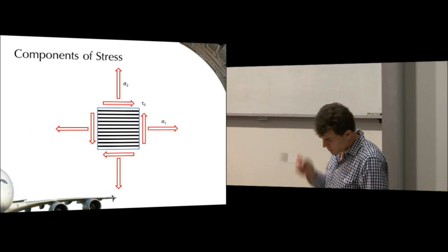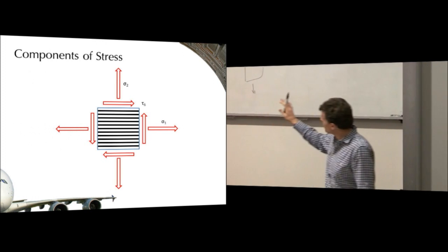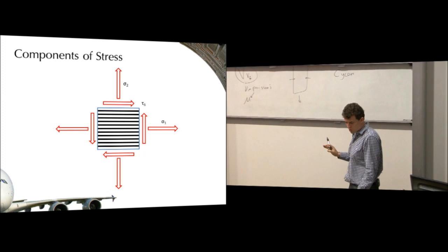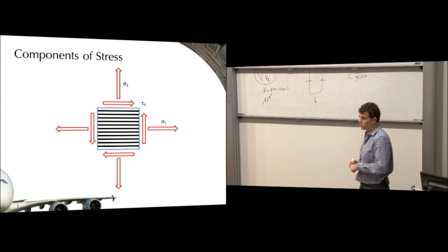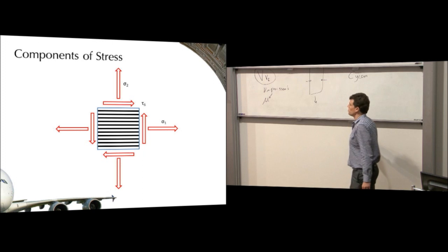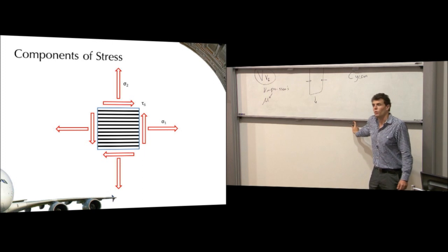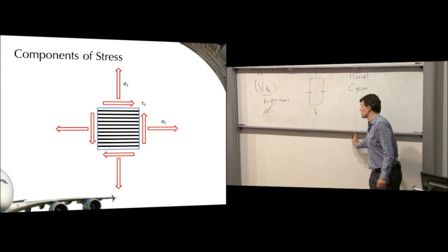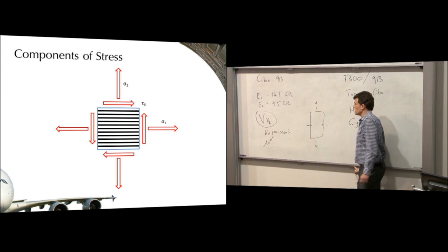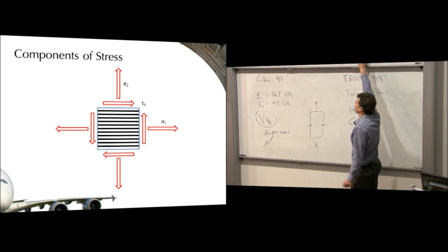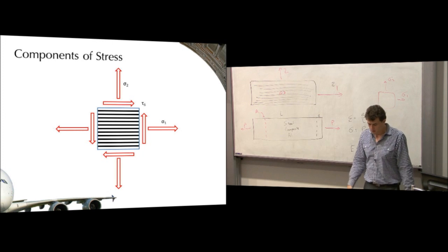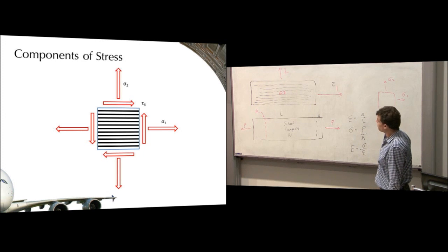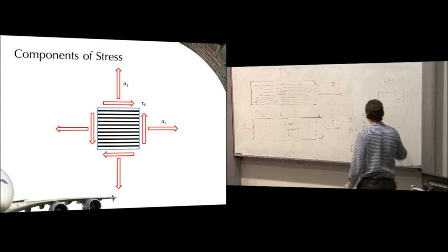Okay. So we've looked at predicting the elasticity in one direction, but we know these materials are anisotropic, and the way we've done them at the moment, they're orthotropic too, because the three axes are independent of one another. When we make a laminate it doesn't have to be orthotropic, but in this case, because we've only got a one-directional lamina, it is guaranteed to be orthotropic.